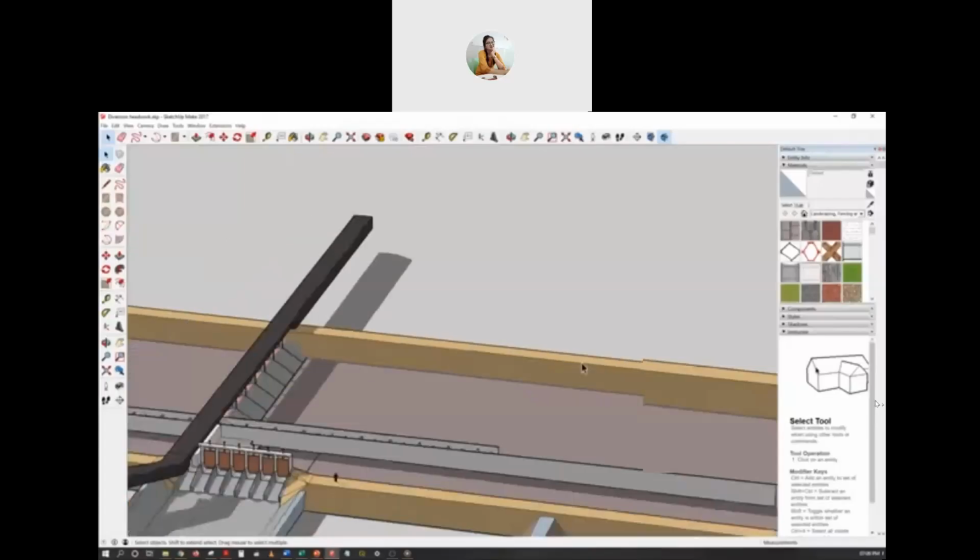So water comes in from this direction, and here it is stored and the level is raised because of this weir, and this divide wall makes sure that in this portion the water is not having lots of secondary currents or eddies.